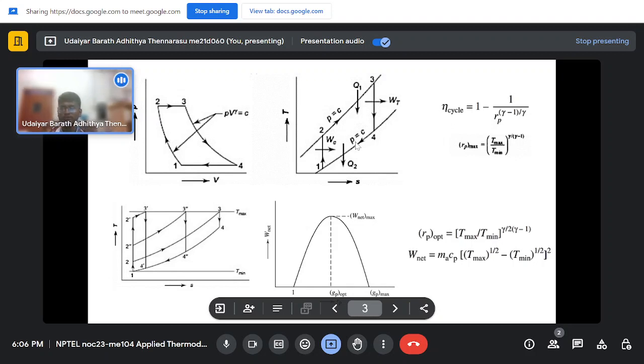If you're going from one single stage to two stages, you have two compressors and two evaporators, so your pressure stages are different. Now the maximum compression ratio will not be P4 by P3, but you will have an intermediate pressure. So you will compress it to that, reject some heat, and then compress it again.